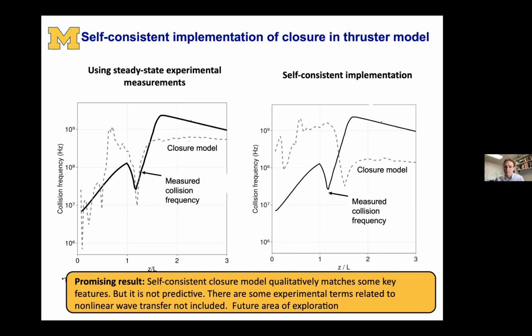Yeah, the short answer is, if you have enough computational speed, I don't think 3D PIC is intractable for this problem. The reason why it is intractable right now, I think, falls under both camps that you alluded to. To get this effect, you have to model the electron dynamics in addition to the ions, and so that requires very small time steps, effectively. And to be sure, there are people that have recently done 3D PIC on a Hall thruster, but it was in a reduced dimensional thruster, so much smaller than an actual thruster, in order to save on computational expense.